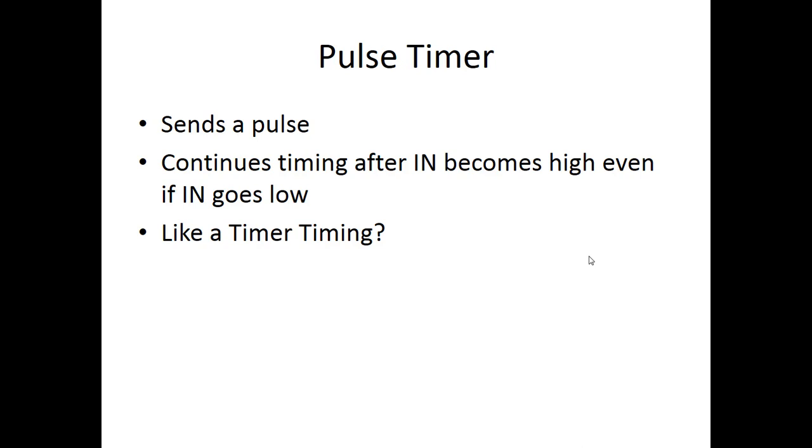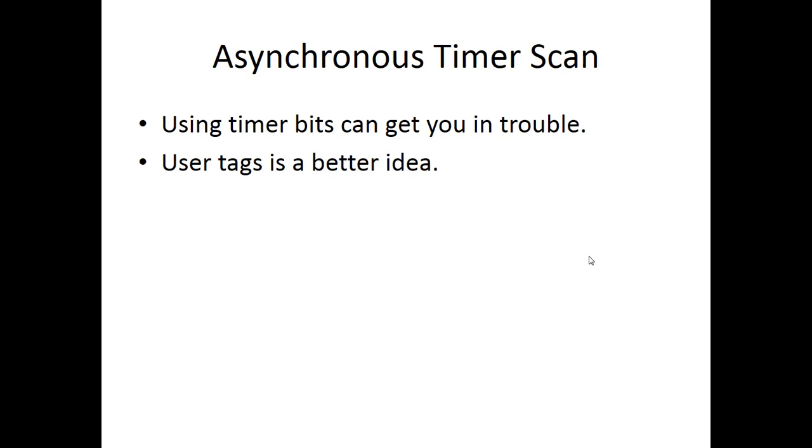Similar to maybe a timer timing bit, but a lot of times it would be used for sending some type of an interlock or crosstalk interlock to another controller, because if you wanted a brief quarter second, you could just close a contact for one scan, and then it'd pulse on for a quarter second or something.